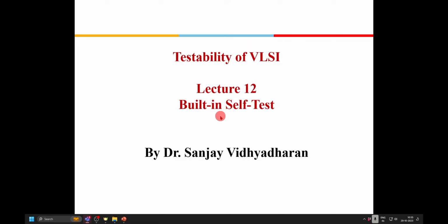Okay, today we'll take on a new topic which is known as built-in test. All this while in this course, we had discussed how various faults can be diagnosed in a chip post fabrication: what kind of test vectors we require to identify the faults which occur, and how, post fabrication, to put the chip on a test bench with automatic test equipment that gives the test vectors, then see the results and compare them with what is expected, and decide whether the chip passes or fails if it doesn't meet the specifications. That is what we did till now.